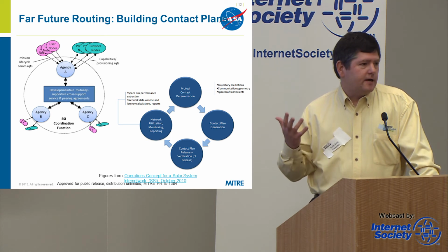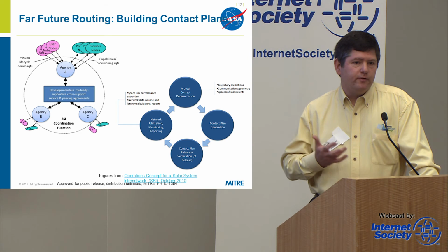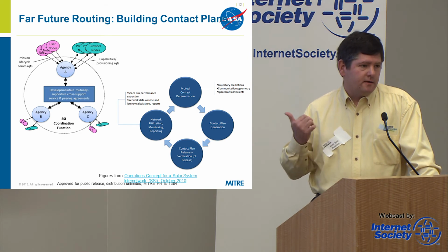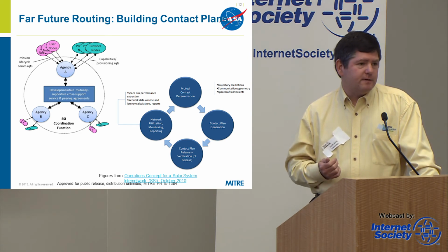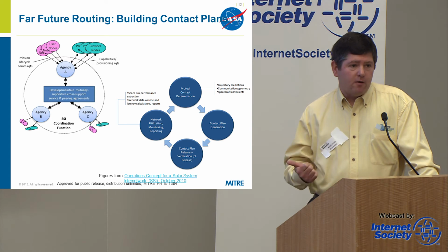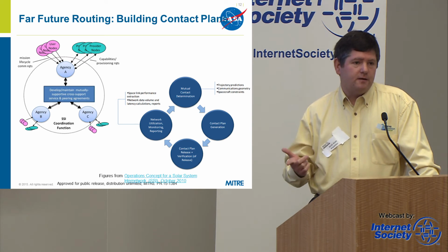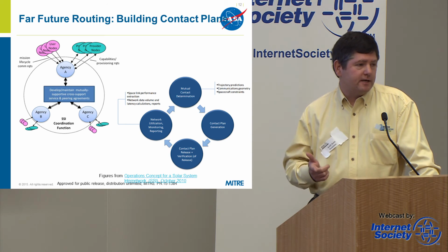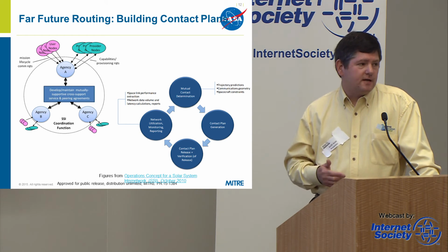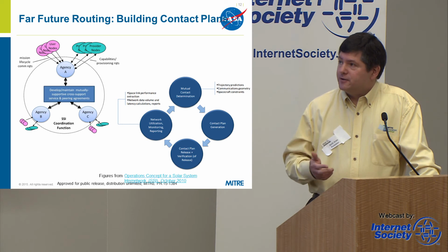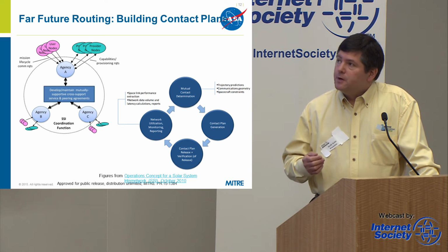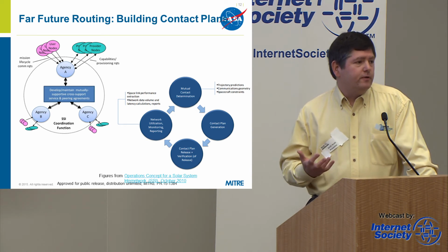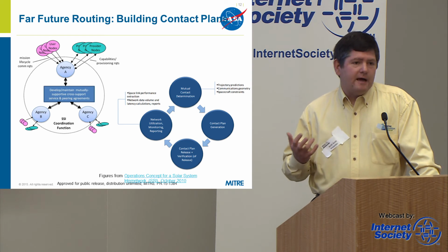In building the contact plans, we're going to have to live within what the spacecraft does, because there's somebody who's the mission manager for that spacecraft. They've got an idea of what the power budget is, and whether you are going to cause a vibration by slewing the spacecraft that's going to get in the way of its science mission. What other bad things are you going to be able to do? So we've got to be able to live within that box. At the same time,